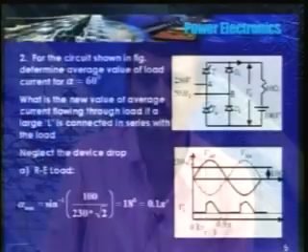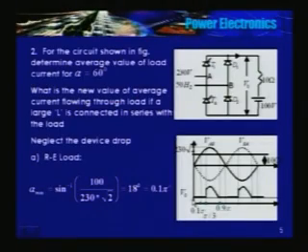So from 0 to 60 degrees, output voltage is 100 volts. At 60 degrees, you have triggered the bridge. So T1 and D2 start conducting in the positive half. The equivalent circuit is T1, load, D2, back to source.